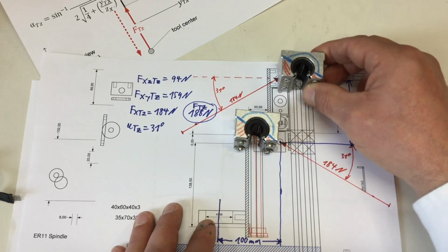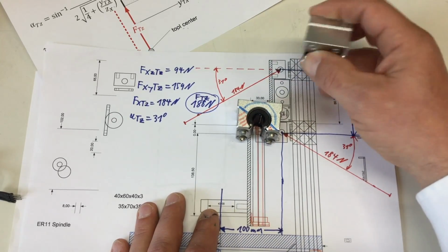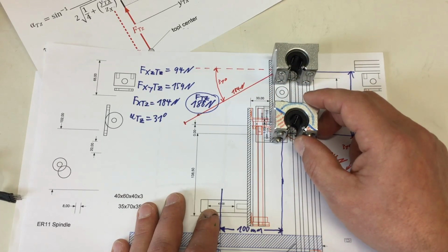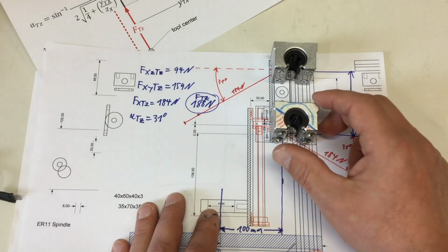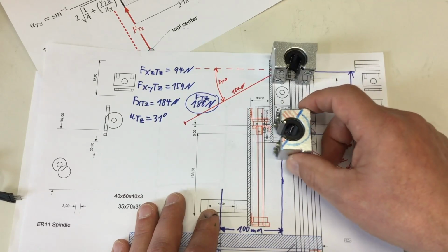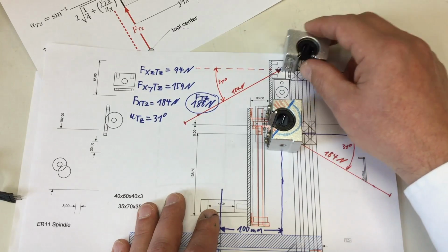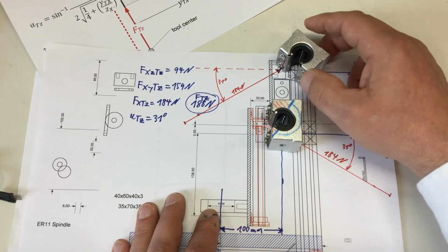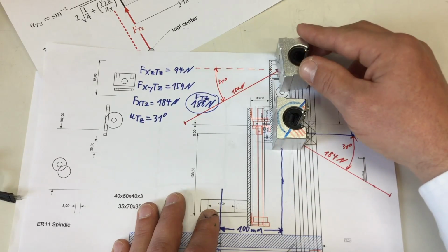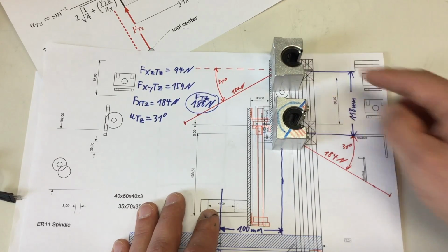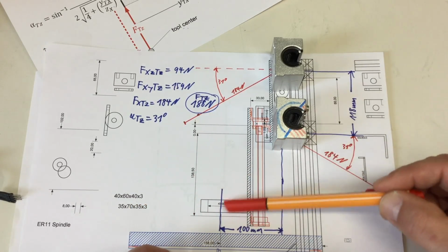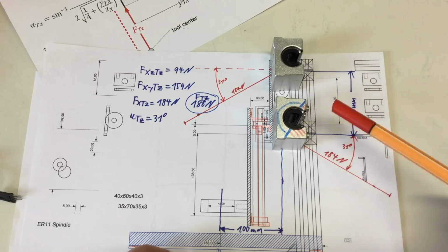Simply in your hand, turn it around. So I could install them this way, but there's no way, you see my drawing, that I can install them this way. Sorry, other way around. This would not work at all, because as I said, if you got a negative force on your spindle, forces would come from here.